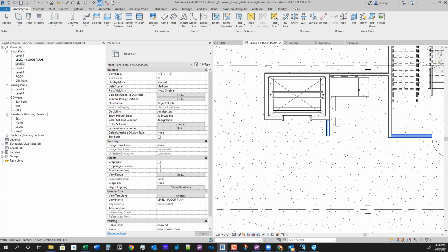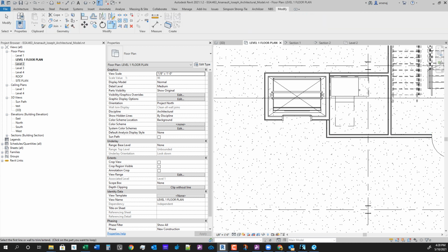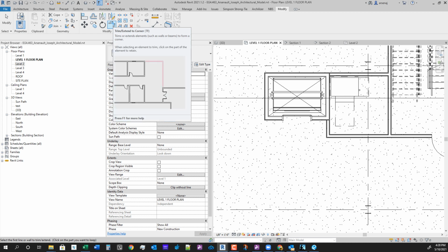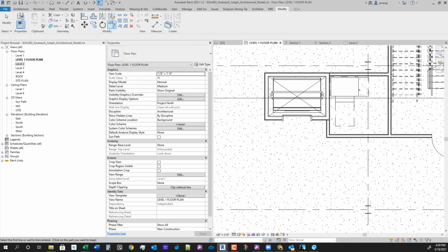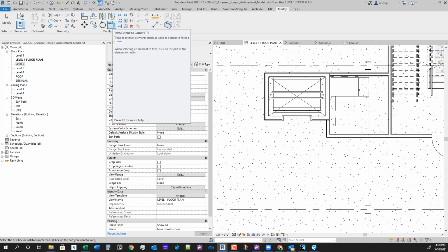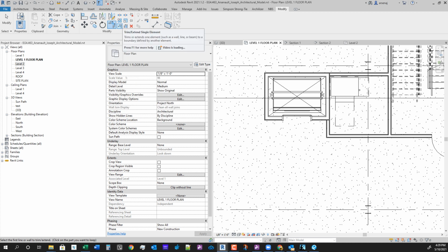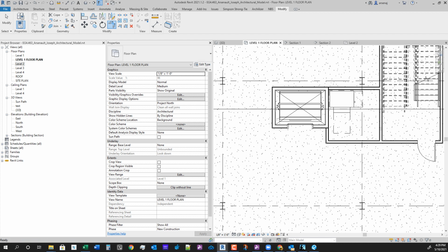So we'll trim the corner. So fillet. I keep mentioning when talking to some of you guys that it's kind of confusing. This trim extend corner really should be called fillet, because that's kind of what it does. It's more like AutoCAD's fillet than a trim corner. It makes sense, but it brings up, if you've used AutoCAD a lot, that the trim extend is more like the trim extend in AutoCAD. This is more like the fillet command. Except I don't think you can actually apply a radius when you do the fillet. It would have to be afterwards.